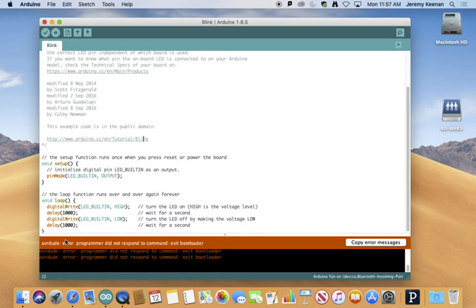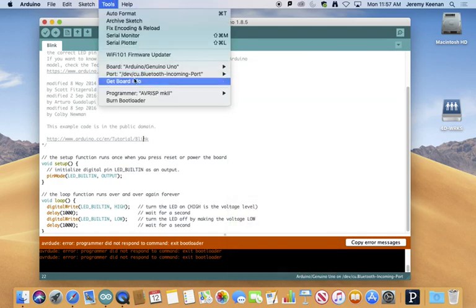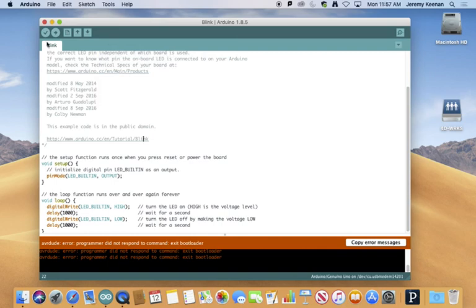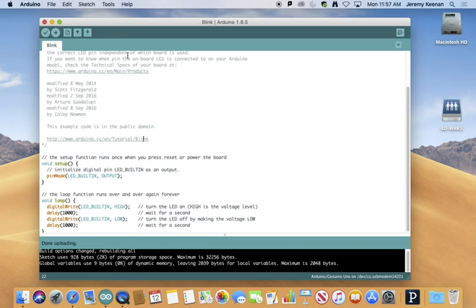And for now, all I'm going to do is actually plug and unplug the Arduino from the USB cable. And I'm going to reselect my Arduino Uno and select it here in the ports menu and try and upload again. And that's it. So this happens from time to time when working with Arduino, and usually all you need to do is unplug the Arduino and reseat the cable.